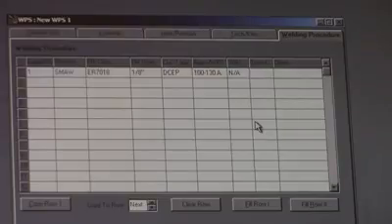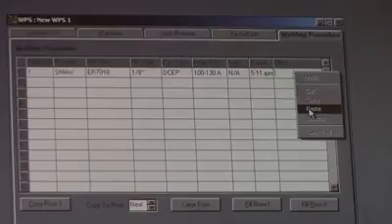Because it's vertical up, they might travel really fast doing a stringer and do multiple stringers. So I would probably say somewhere around 5 to 11 inches per minute. That's going to ask you for other. If there's some other thing you want to put in here, you can, but we're not going to.